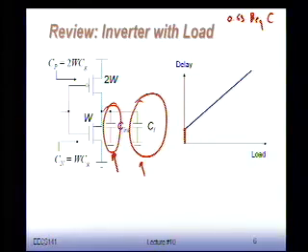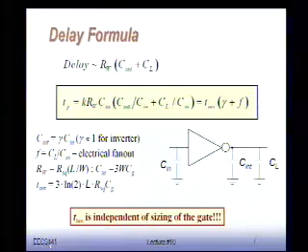And actually, the beauty of the equation we're going to go after is that this intrinsic capacitance is kind of a nasty parameter. It's an internal parameter that sits in between. What I would like to do is express the delay as a function of what I see as the input capacitance, because that's going to determine the load for the previous stage, and the load capacitance CL, which is the load of the next stage. If I can do that and use only those parameters, I can start chaining things together in a very methodological fashion. So let's play around with this equation.